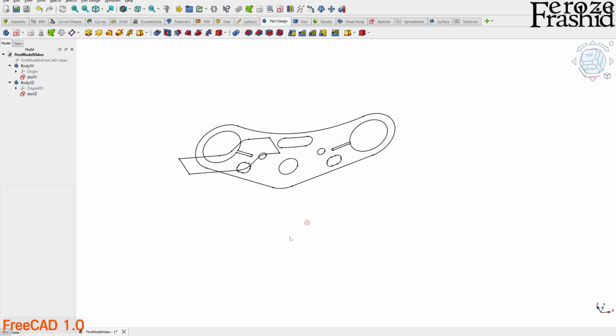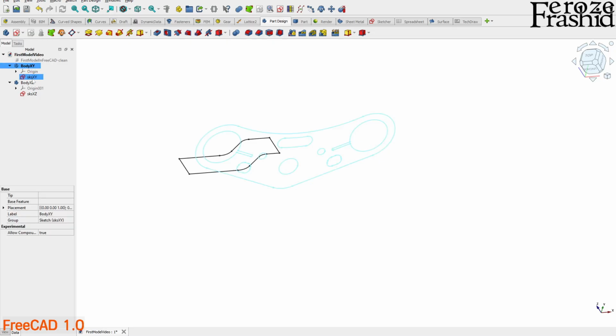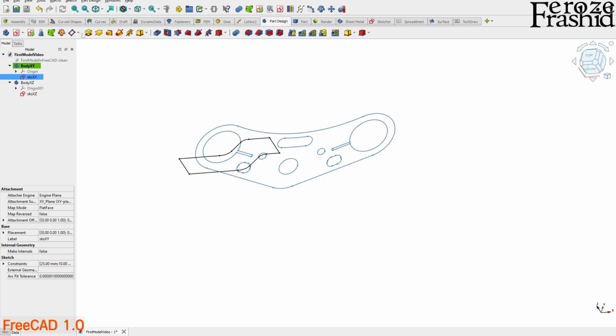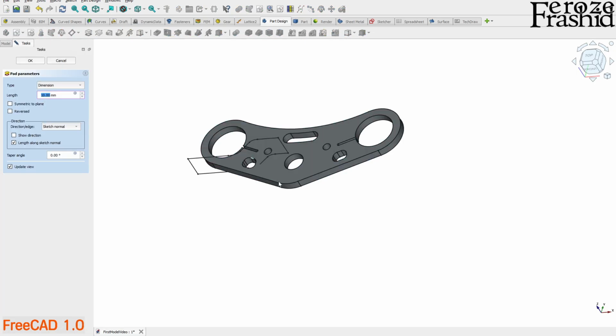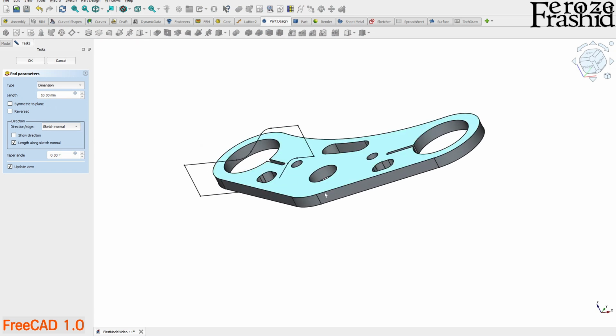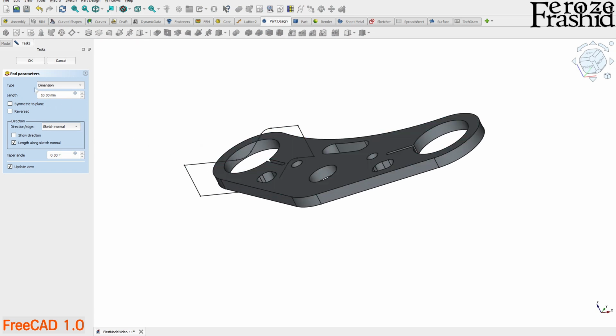So I want to build this base model by having a common between these two models from these two sketches. So I want to extrude them. I want to give some 3D shape to these two-dimensional sketches. So I want to get into first model, activate it, select this sketch, and come over in the toolbar and pad it.